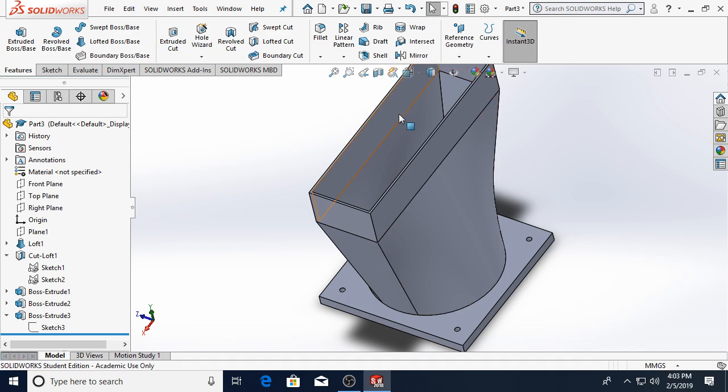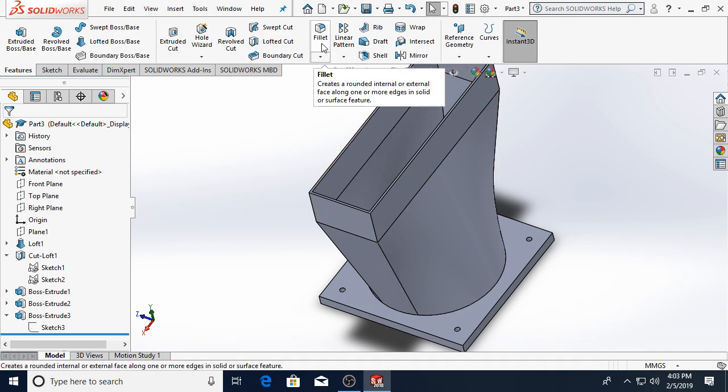So in this case, the first thing that we have is a fillet option. You'll remember earlier, about 20 minutes ago, when I was trying to create the shape of a handle to extrude, I had used a fillet on a sketch. I also have the ability to create a fillet on three-dimensional features. The logic is the same. It creates a roundover that connects two intersecting faces; they don't even need to be perpendicular.